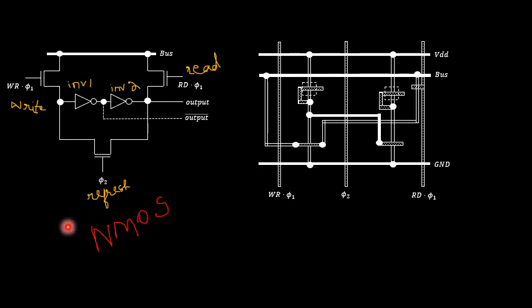We have already studied the timing considerations initially in the memory unit, wherein we discussed that a two-phase clocking system is used, that is phi 1 as well as phi 2 clock phases. They will be mutually exclusive in nature. Phi 1 is the clock signal used to perform the write as well as the read operation, whereas the phi 2 signal is used to perform the refresh operation.